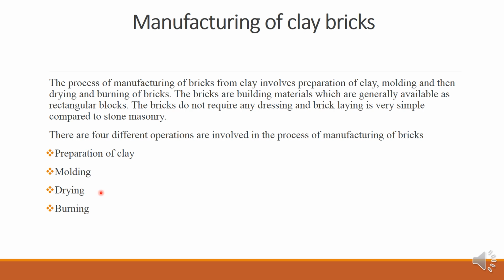Coming to the preparation of clay, blending is another important thing. If you add any ingredient to the clay, it is to be added in this stage by making the clay loose and spreading the ingredient over it. Next, tempering. It is the final stage of preparation of clay. In this stage, water is added to the clay and pressed or mixed. The pressing will be done by cattle or with the feet of men for a small scale project. For a large scale project, we have to use a mill or grinder.